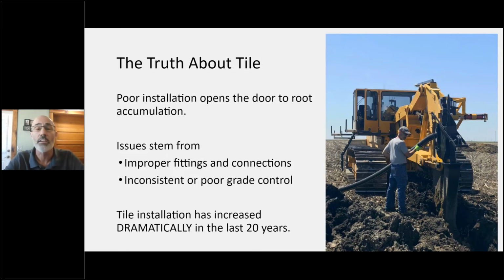My own tiling contractor has said, yes, he has seen once where annual rye had plugged a tile main. But when you ask more questions, they were quick to say, here was the problem. It was waterway work that was being done. They put tile in the waterway and the farmer seeded it down after installation to annual ryegrass, and he let it grow very thick. That is a cover crop which can cause some issues, but it was a case where that cover crop in the waterway should not have been used at the depth that it was. You can find those problems, but ask questions and find out why.